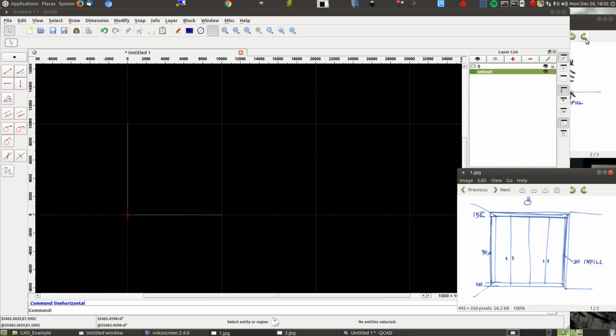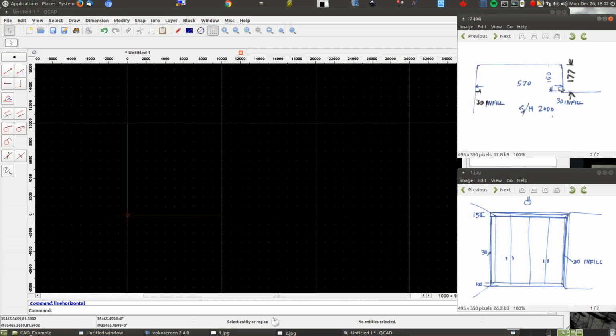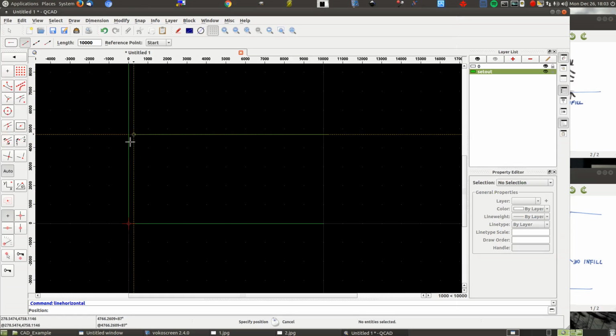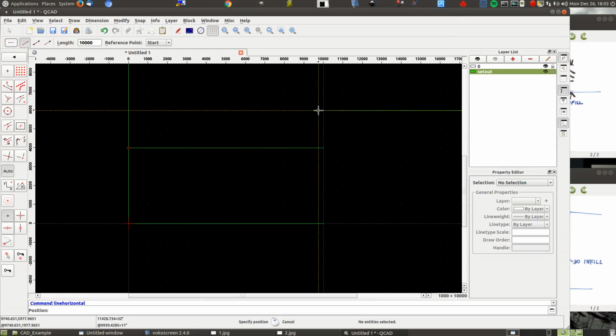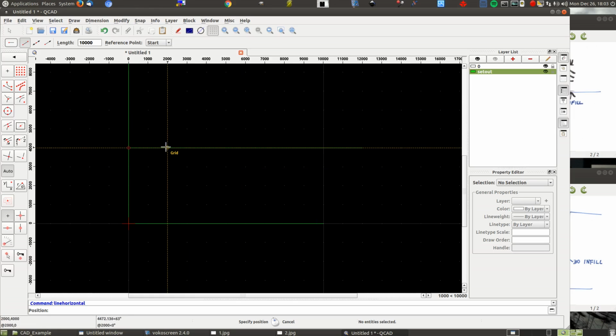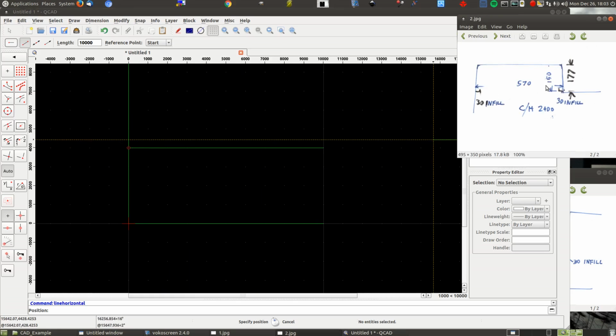Now, looking at this job, the ceiling height that I noticed I've written on my sketch here is 2400. Okay, so it's 2.5 meters roughly, 2.4 meters. Each one of these dots is at a 1 meter space. You can see 1,000 millimeters, 2,000, 3,000, and so on. Okay, so I'm going to draw another horizontal line at the 4 meter mark. It'll make more sense as it gets going. Right. Now that's where I intend to work as the back wall of this plan view.